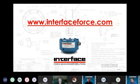Yeah, well, typically the best connection is a welded hermetic connection with, say, a submersible cable. Certain connectors are better than others. Some of them have O-rings and things we can specify. They're actually undersea connectors that we can specify. We use them on some of our load pins and load shackles. They're used underwater. Typical connectors, though, especially in the back shell of the mating connector, might be a leak path.